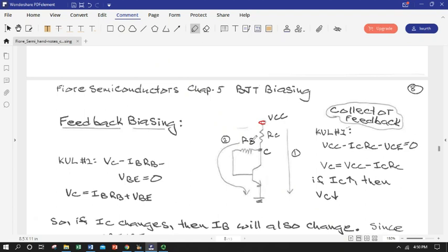If we define the voltage at C as effectively, in this case, equal to the collector emitter voltage drop, because there is nothing else in the circuit between it and ground, we can substitute V sub C in for VCE and say the voltage at point C is simply the collector supply minus collector current times collector biasing resistor.